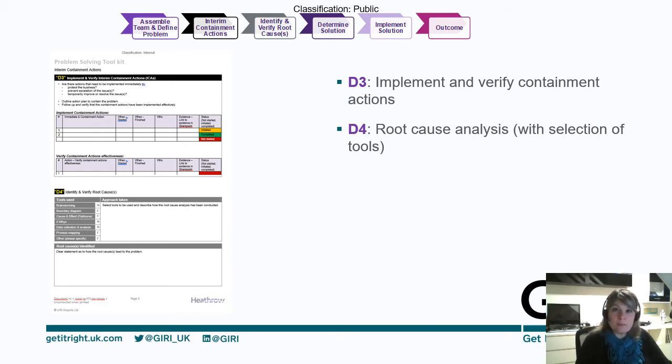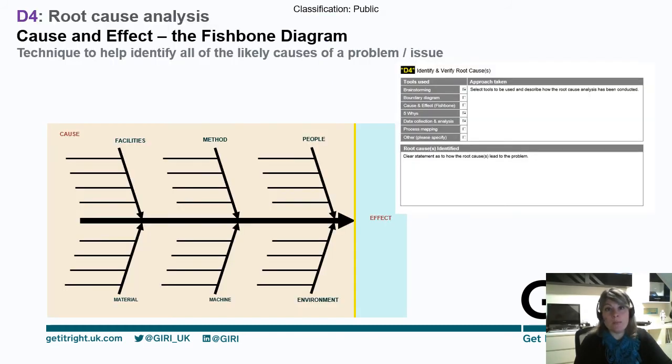When you have contained the problem, you know you're not producing any more problematic joints, assemblies, or product. You know that you have contained any health and safety risks. That's when you actually focus on root cause analysis. Then the team can focus on root cause analysis knowing that they have contained the problem.